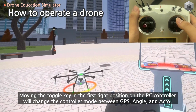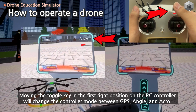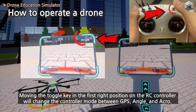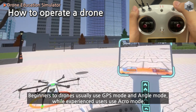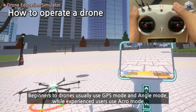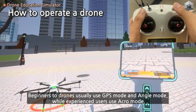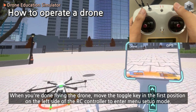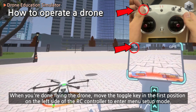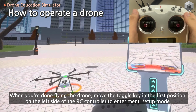Moving the toggle key in the first right position on the RC controller will change the controller mode between GPS, angle, and acro. Beginners to drones usually use GPS mode and angle mode, while experienced users use acro mode. When you're done flying the drone, move the toggle key in the first position on the left side of the RC controller to enter menu setup mode.